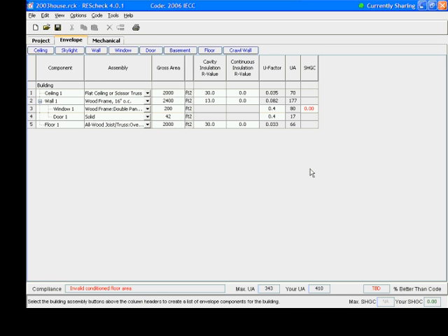If you had glazing in the 2003 that was higher than 15, 15 is typically the baseline back in the 2003 as far as the compliance for window-to-wall ratio. Let's say if it was at 18 or 20 in the 2003, well, believe me, stringency was increased when you were trying to show compliance for that higher glazing in the 2003. And most likely, bringing in a project to the 2006 that had a high amount of glazing, such as that, probably was meeting code in the 2006 because your stringency had increased significantly for that higher amount of glazing. So again, we've actually made an FAQ that kind of explains this.